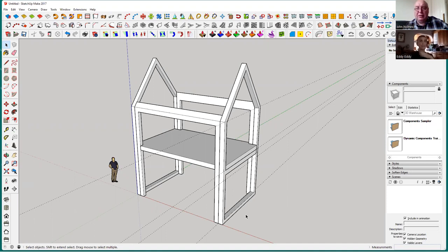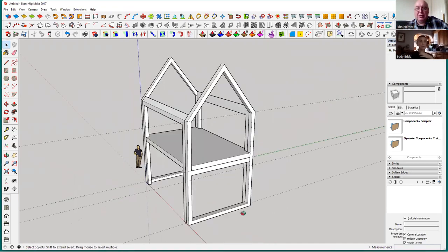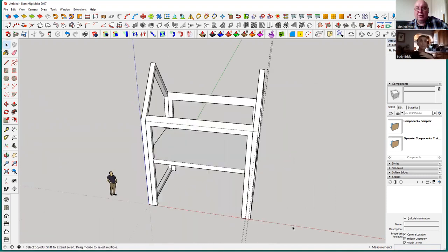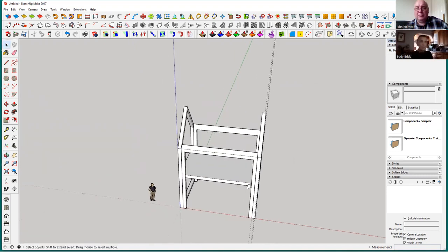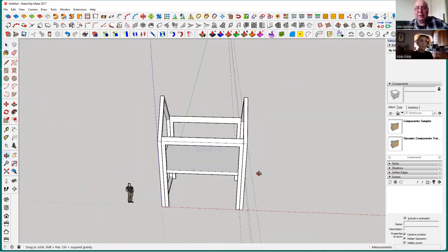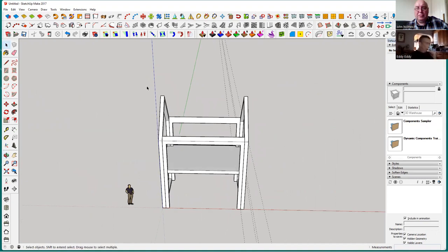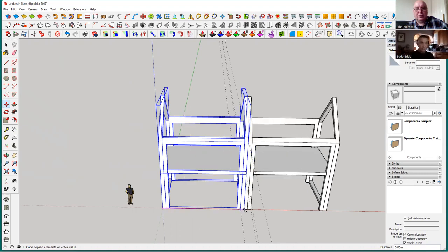If you look at it now, you can modify that any way you like to make whatever building you like. You know, if you want a row of houses, highlight, click the move tool, control to duplicate it along the red axis, which is the right hand button, move along.